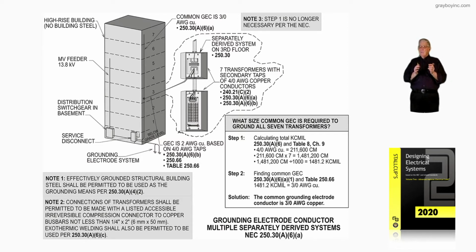But notice it's not unusual to set a K-rated isolation transformer on each floor to feed isolation receptacles, 250.146(D), as in dog, to cord and plug connect equipment or hardwire sensitive electronic equipment in accordance with 250.96(B) that we kind of reviewed.